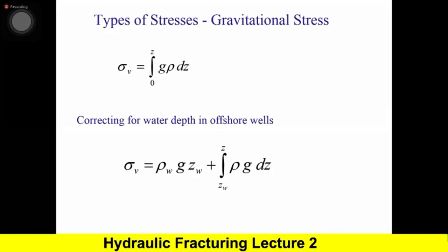If I give you a formation and say we have all this formation, here is the specific gravity of each rock. Some of them may be 3.6, maybe less, multiplied by 0.433. If it is sandstone, it is approximately 2.65, so 2.65 times 0.433 is about 1.1 psi per foot. But if I give you the information, you need to do it correctly. You can do it easily, and that's exactly what the log would do when they calculate stress for you.